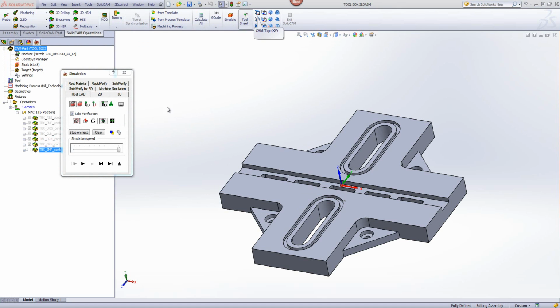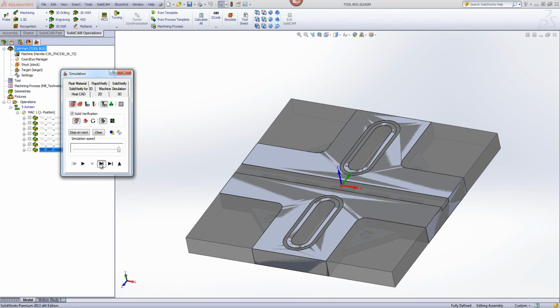Simulate. You can see the tool will go down outside of the part and go across. Now look at what happens over here. It doesn't go up to get to the next wall. It goes directly across to the other side, two separate chains, and comes back. Now it's going to do its finish across. Sorry, I did it a little bit too quick.